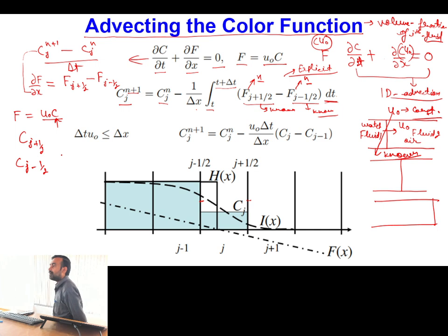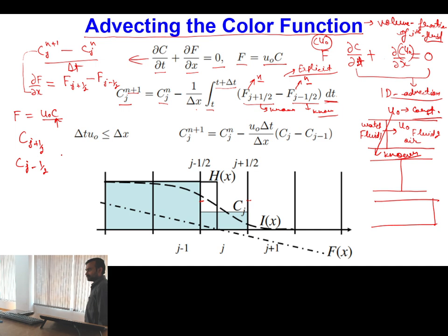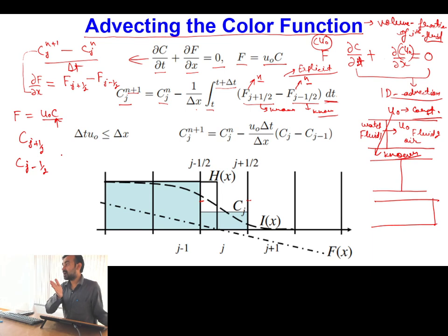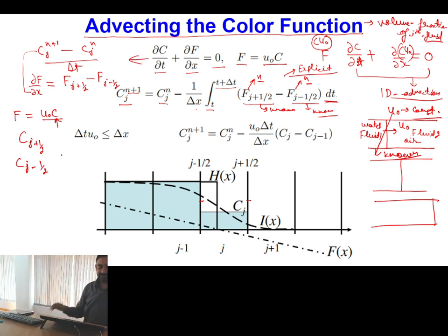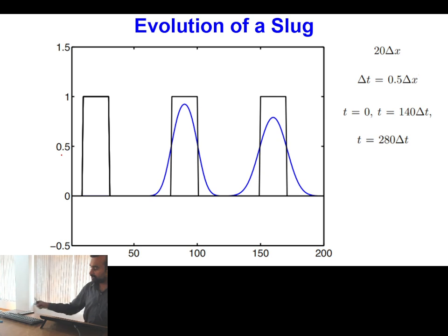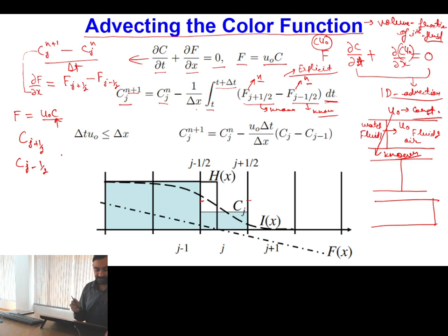Central difference scheme or upwind differencing schemes? For the convective term, because we have to take into account the effect of flow direction, the transportive behavior of the numerical scheme should be satisfied. So that's why we will be choosing the upwind scheme.